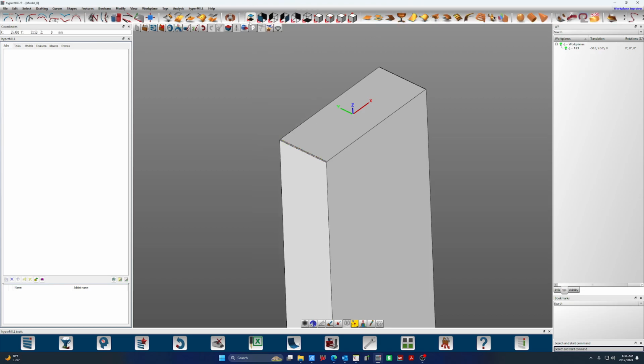Workplane views kind of go hand in hand with the Workplane toolbar and orientation. This is where this goes hand in hand. Why putting work planes on faces and setting your view normal is, I think, a great way to navigate is, again, because we can do something without ever having our hands leave our keyboard or our 3D mouse, which is if we use the Alt key and X, Y, Z, we can manipulate the work plane around any one of its vectors.